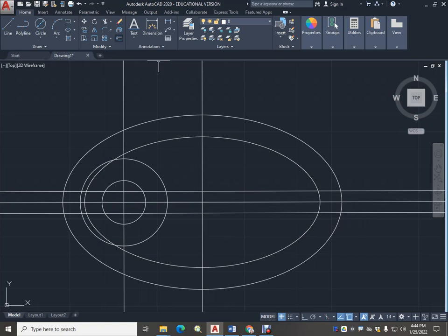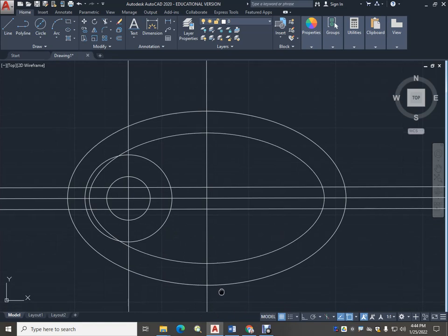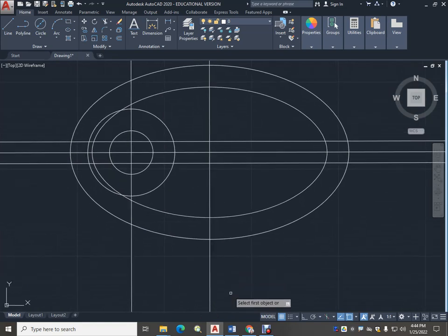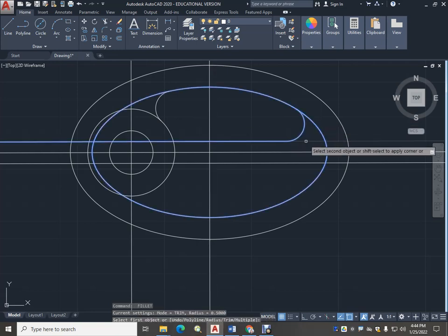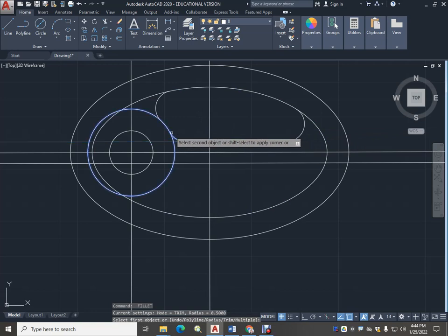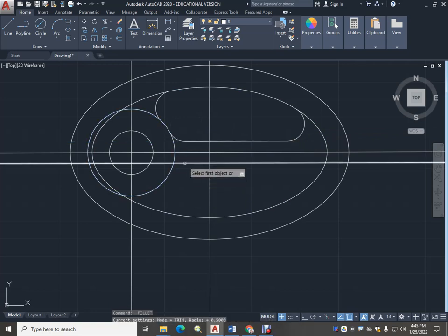So it's telling us that we have fillets of 0.5. Typically the command bar will pop up and give you that information, but I don't know why it's not doing it. But I can hit R for radius, and now it'll ask me for that radius. And we want 0.5. Now we'll go ahead and fillet those radiuses. I'm going to arm it again with the space bar. And one more on this side. Again, let's repeat.